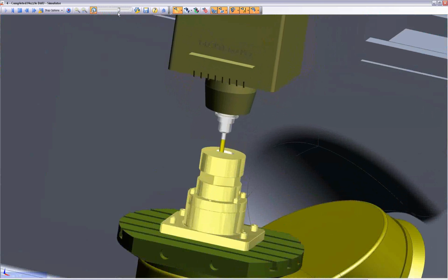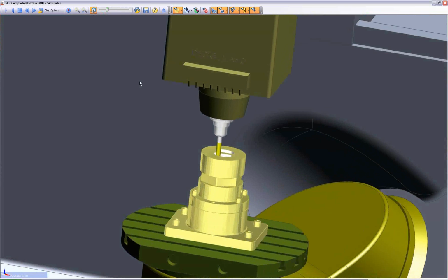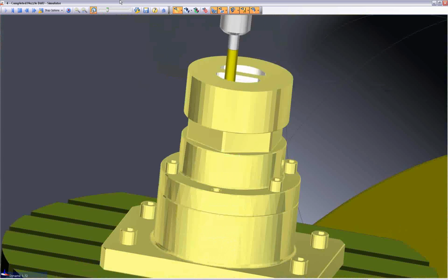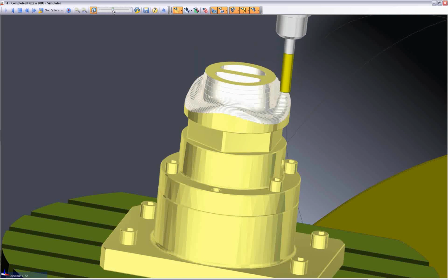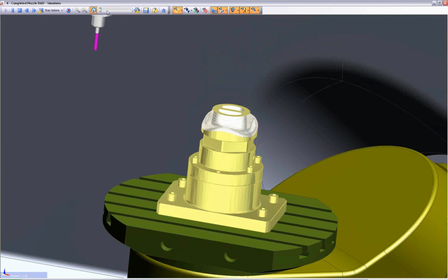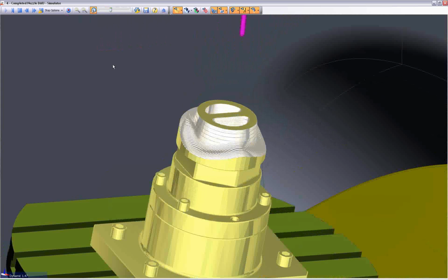We guarantee 0 collisions in our software. This is because we can check the toolpaths in what we see now, the Edgecam Machine Tool Simulator. Not only can we check the kinematics of the machine tool, but we can check for holder collision against the stock, and tool collision against the components. As we can see now, the toolpath is beginning to generate a rough toolpath.